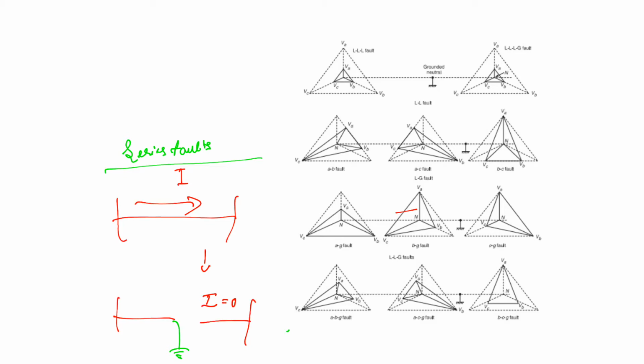However, in practice, it is observed that most of the series faults, which are also known as open conductor faults, sooner or later develop into the short circuit faults that we have discussed. However, there are some instances where the open circuit has very dangerous consequences.